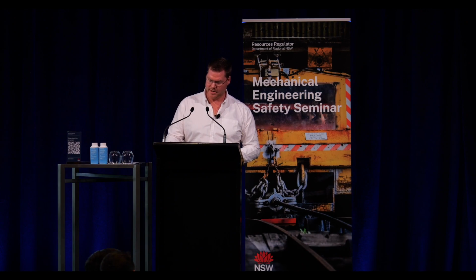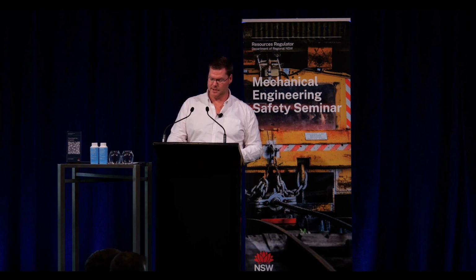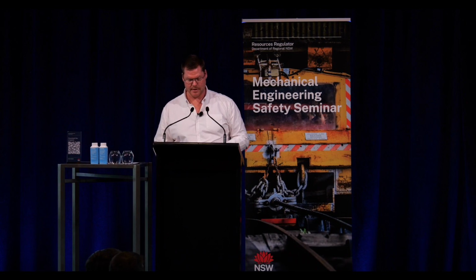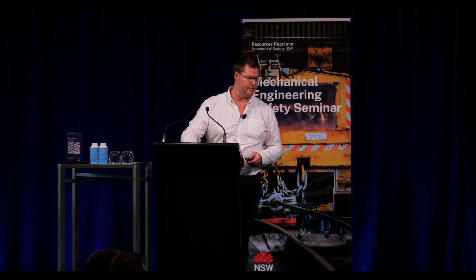Then there's the possible introduction of an idler sheave into the system. These can be installed to guide the rope and help achieve the correct fleet angle. For new or upgraded systems, we can also consider a rope type that can handle higher fleet angles.